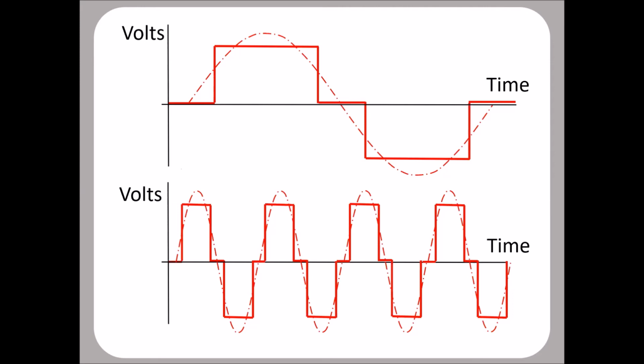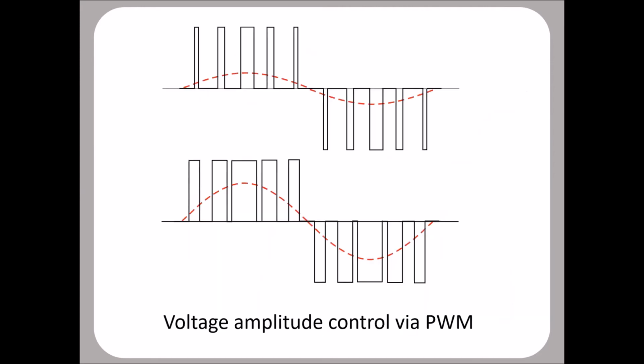And the way that's done is by saying, well, we've got this switching circuit. Why don't we switch on and off during the half cycle? And you'll see at the top, we've got a lowish fundamental component shown by the red line. And we've increased that in the bottom one by widening the on pulses during the positive half cycle. And that's called pulse width modulation. It's almost universal now, but it was totally unthinkable when I was a student. There was no way we could contemplate doing that at power levels.